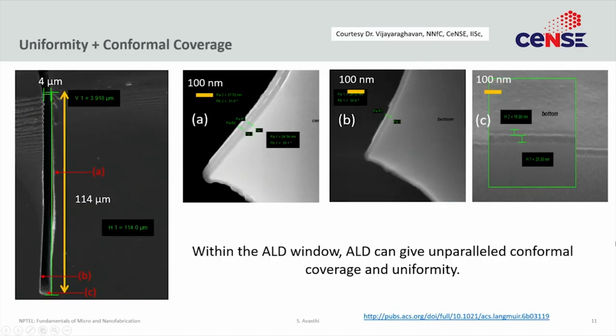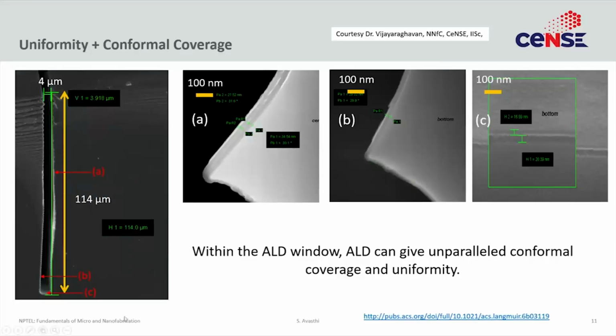And with that, it brings us to something that we started with, which is what is the USP for ALD? Well, the USP for ALD is uniformity and conformality. So if you just look at this slide once, this is something we even saw earlier, but now you can probably appreciate it more, that if you have these very deep channels, right, and you want to coat a very thin layer of conformal aluminum oxide or some other material, that is same thickness on the side, same thickness on the top, same thickness on the bottom, ALD is extremely good.